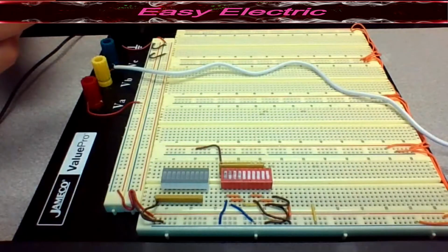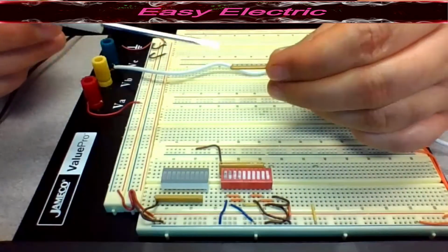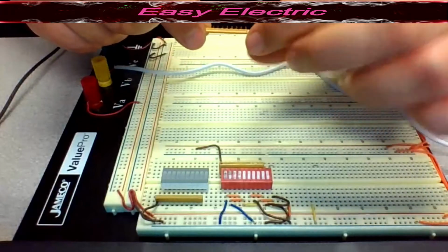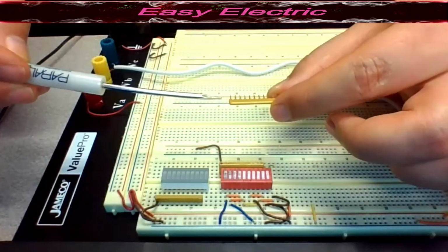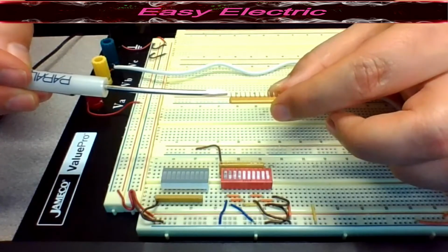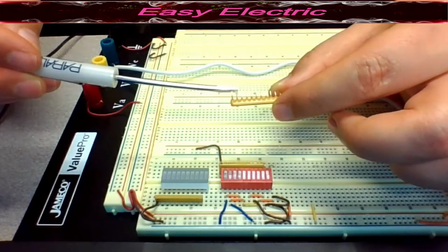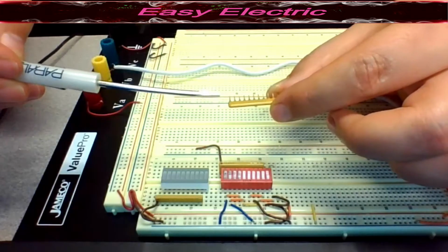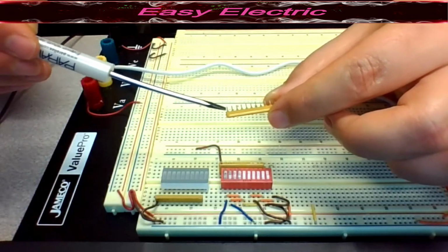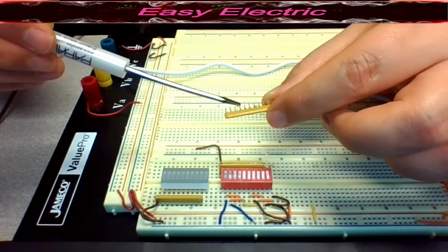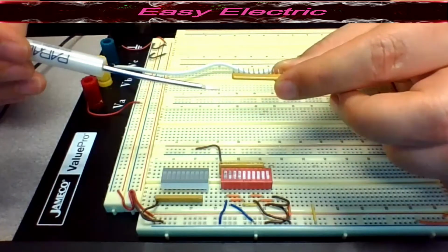So also we have the resistor bar. This is actually too many resistors which they put inside one bar. Usually one pin that you see here is the common pin, and the other pins are the other side of the resistors. So in this resistor bar, I have one common, and I have 1, 2, 3, 4, 5, 6, 7, 8, 9, and 10 resistors.